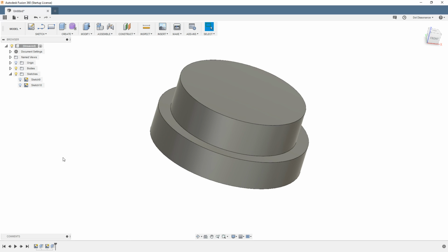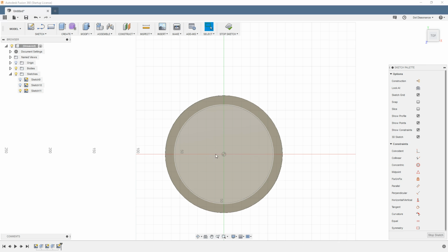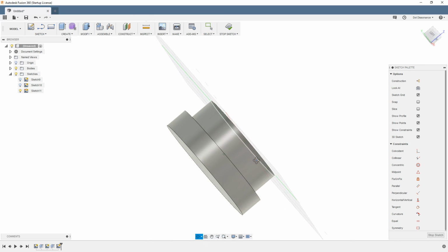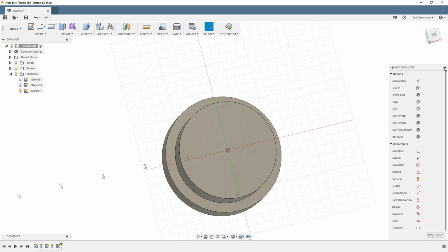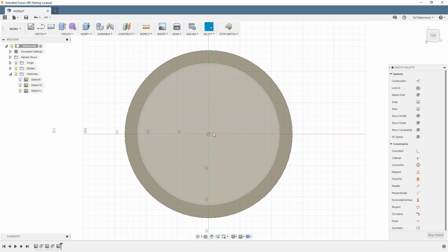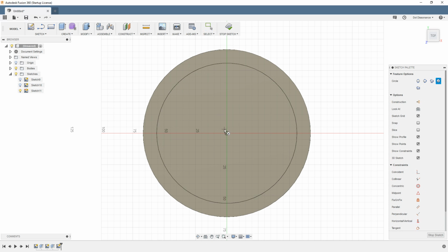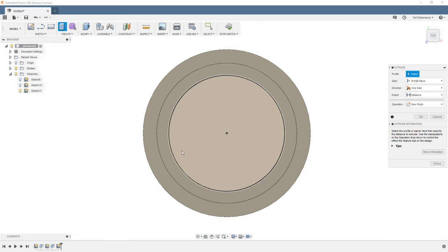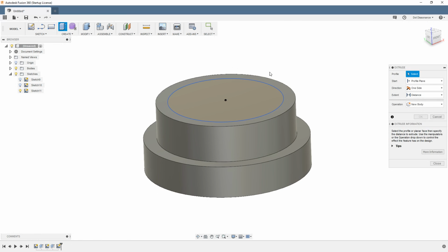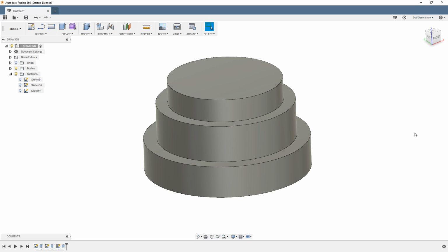Now, let's do it a little bit differently. I can pick this surface, come over here to Sketch, and now I will go into Sketch on that face because I had it pre-selected. Again, you see there it is. Bring it back, flatten the cube out, get this in where you need it, holding down Control and panning it, getting it nice and centered. Hit C for circle, and we'll bring this out, extrude it up, hit E for extrude, take this, bring it up, over and over again. So now we just keep stacking, stacking, stacking.